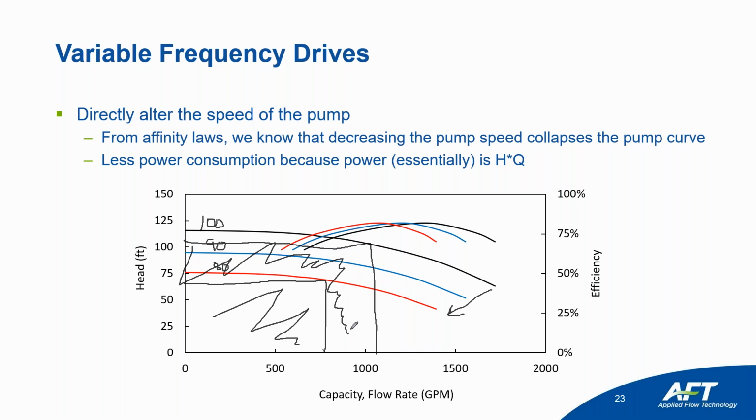Because my area is much lower, you actually have less power consumption, but it makes sense, right? You're adding a whole bunch of power and then taking it away with the control valve, or you can just not add a whole lot to begin with.